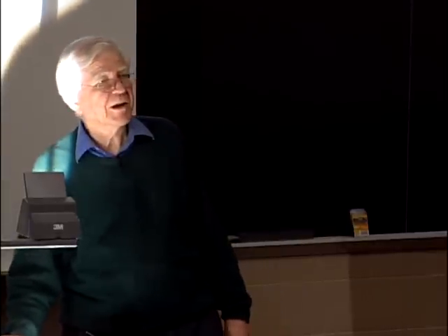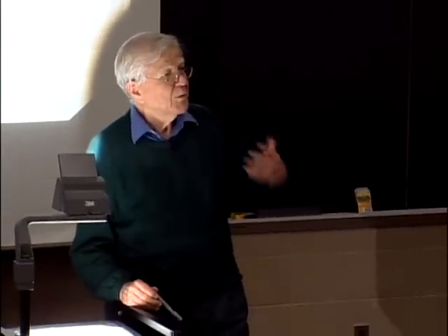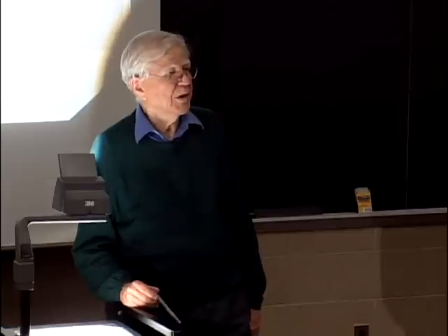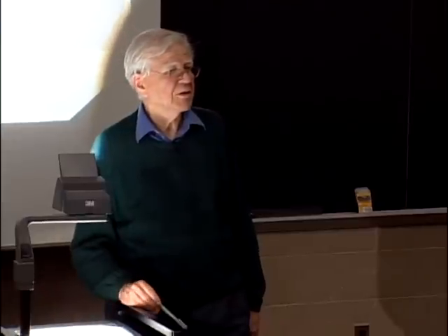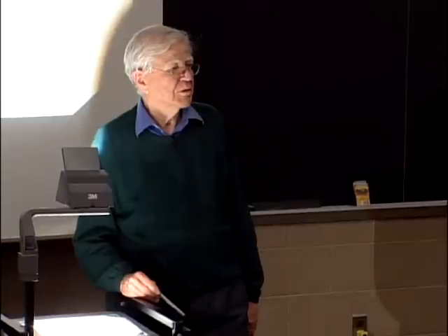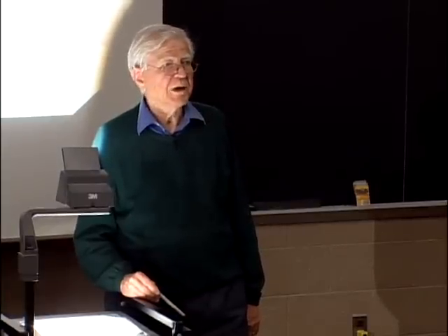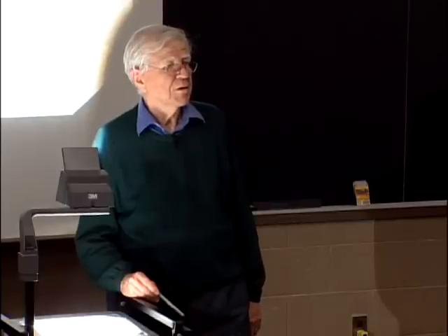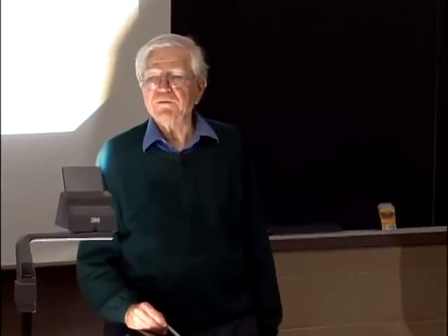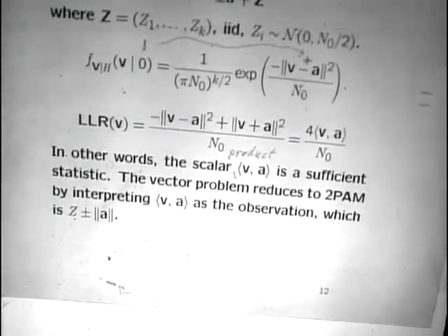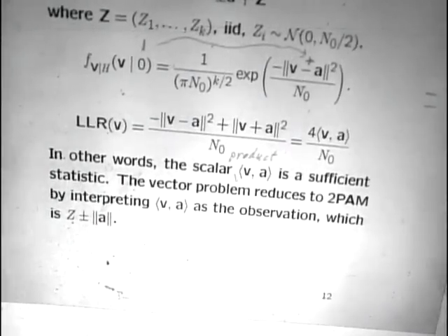You look at what the inner product is then, and then you say, well, what does that correspond to when I deal with L2 waveforms? What's the inner product for L2 waveforms? It's the integral of the product of the waveforms. And how do you form the integral of the product of the waveforms? You take this waveform here, you turn it around, and you call it a matched filter to a, and you take the received waveform, you pass it through the matched filter for a, and you look at the output for it.